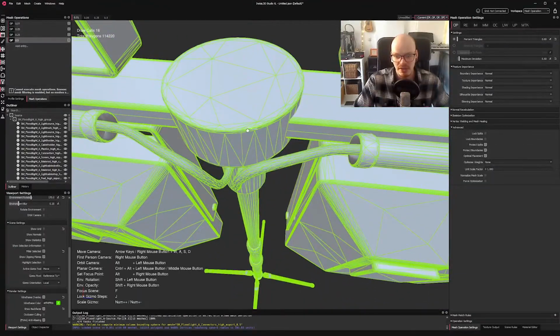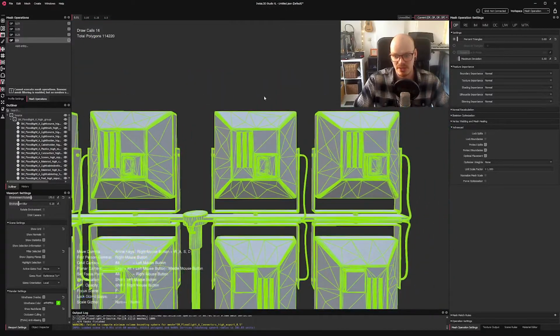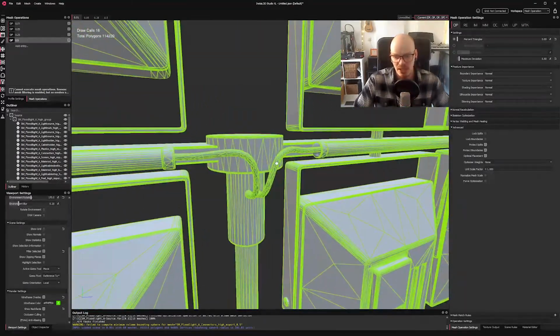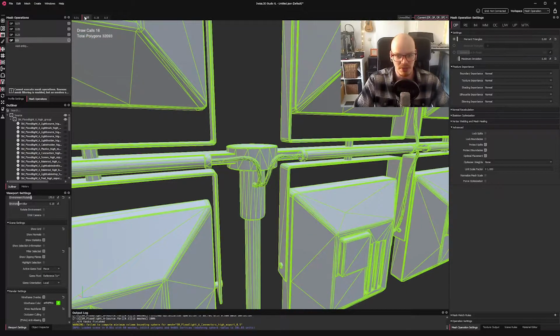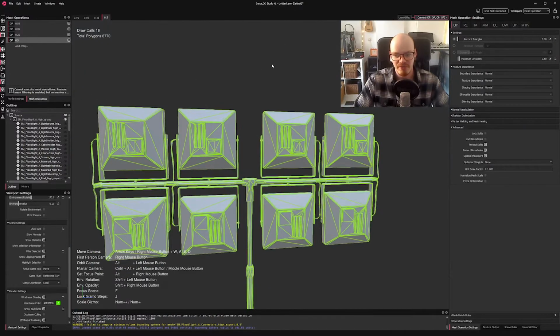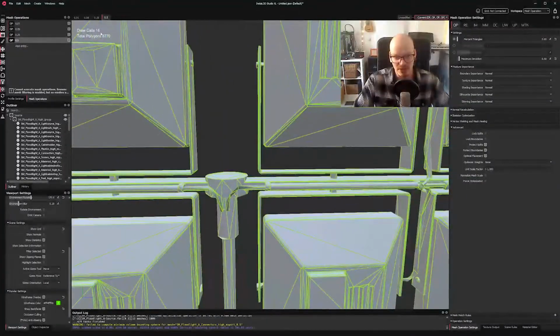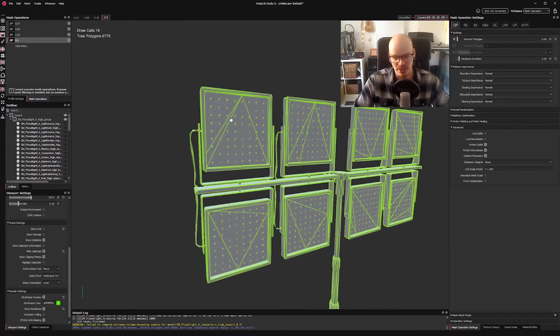Now, if we start looking at the larger deviations, we should see how InstaLOD still maintains the silhouettes and everything perfectly, but simply retains less edges along the curvature and starts making things look a little bit more chunky. So to look at that, we simply have to toggle through these different tabs on top of the viewport. So we can see, there we go, 0.05, 0.25, and 0.5. Now 0.5 is very drastic, and we can see we're down to just 6,500 polygons, which is an incredible optimization.